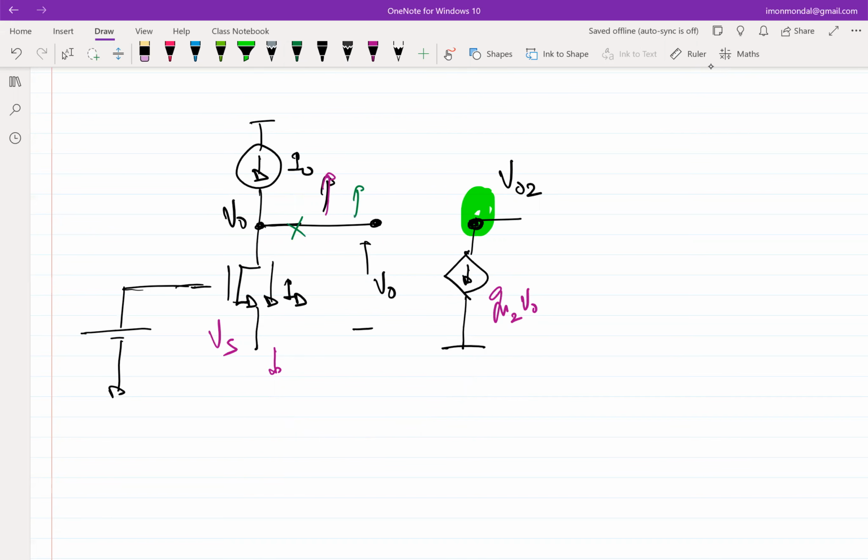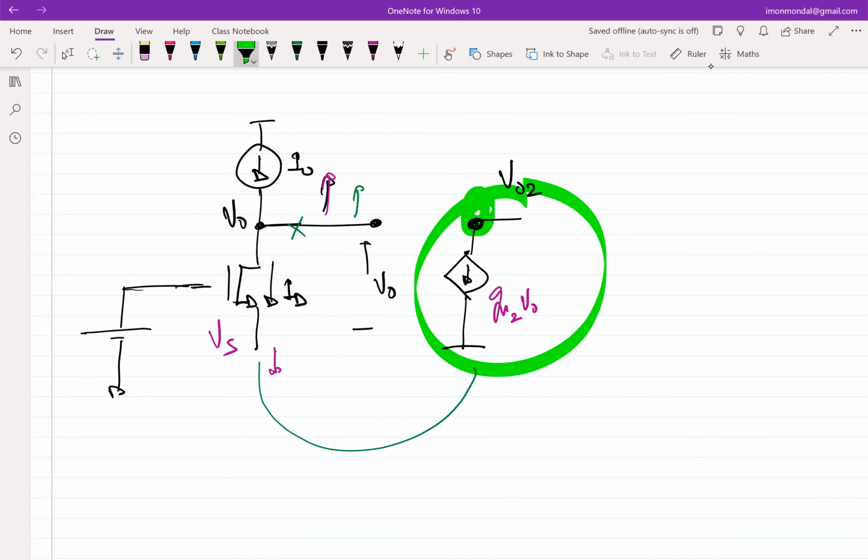And also, you should be able to understand the effect of these things. These are essentially acting as error amplifiers, which means you need high gain. And if you look at the output of the source terminal, you will get low impedance, you will not get high gain, and so on and so forth. So even if the sense of the feedback were right, you wouldn't be able to connect the source directly to this source because you wouldn't have gotten any gain. But that is irrelevant here because the sense of the feedback itself is incorrect.